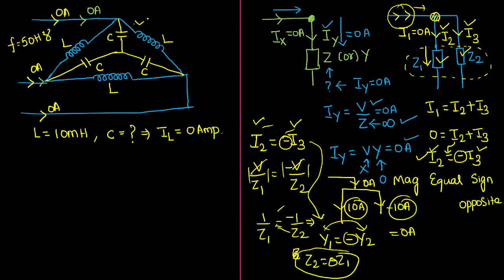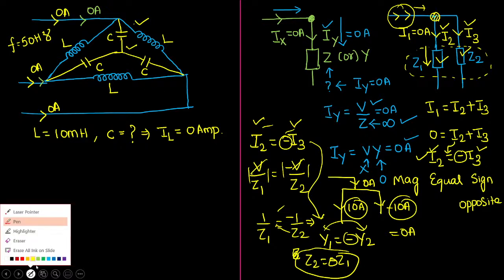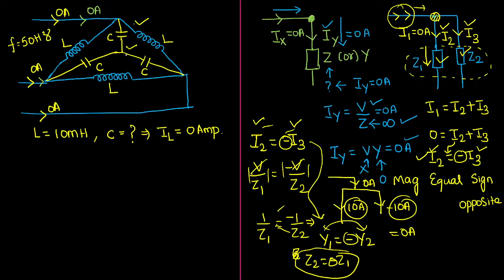See, there is one delta connected network under one star connected network. What I am willing to do is, I just wanted to convert this star connected capacitor into delta connection, because one is in star, another one is in delta. It is too difficult to reduce the network now. Tell me, when three branches are having equal value in case of star connection, when you are converting into delta, how will you calculate the resultant value?